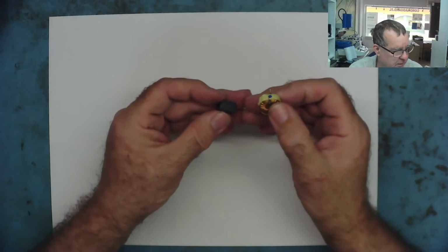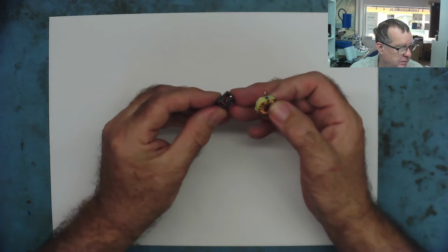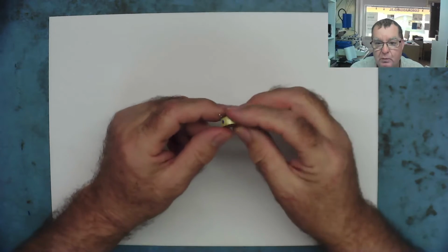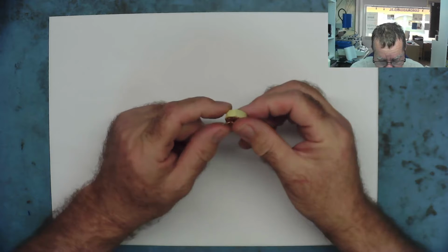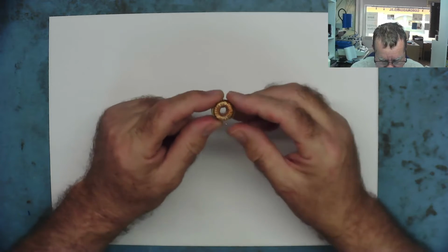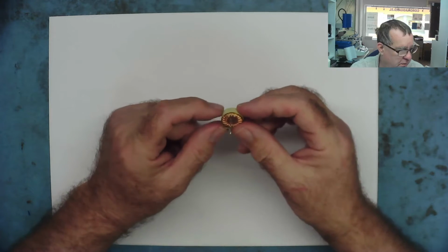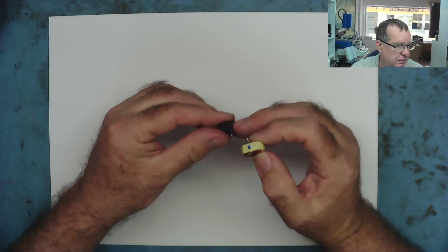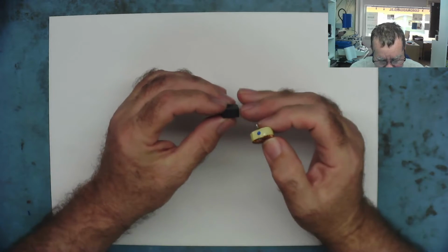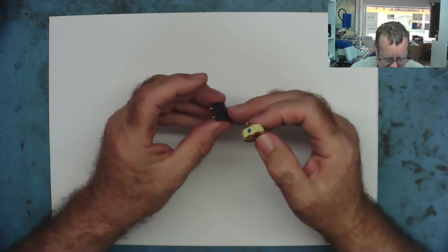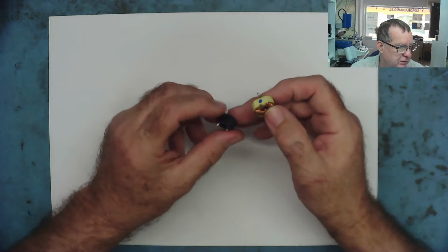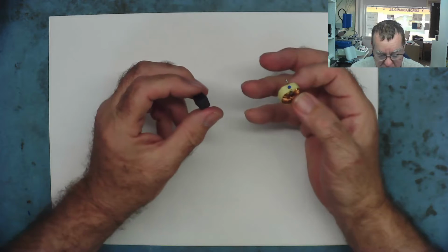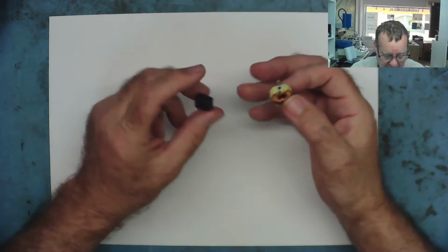So these are some of the surface mount ones that you can see inside. It's just a piece of wire, that's all it is. So there's practically nothing to go wrong with an inductor. There's realistically three ways they could fail. One is physical damage, so the former it's wrapped around gets broken or a chunk gets broken off it. But that's visible, you can easily see that sort of damage. And basically that will reduce the inductance because it reduces the amount of magnetic material in the inductor. So the amount of magnetism it can store is reduced and therefore the inductance is reduced.